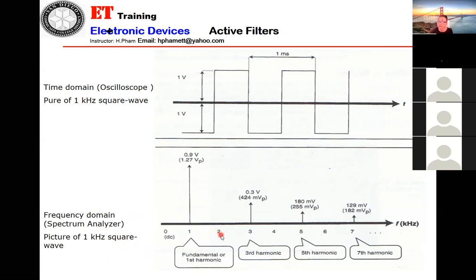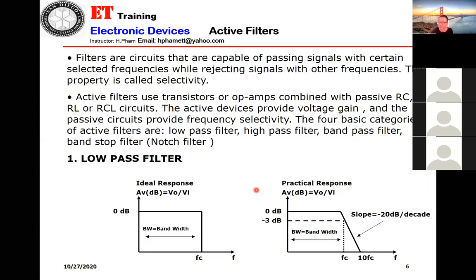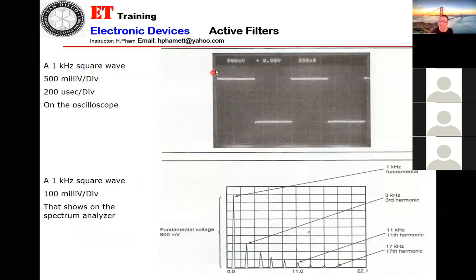They do not display the even harmonics, they display the odd harmonics. Basically, they are telling you at this frequency, 3K, what the value of the signal is. Then 5K, and 7K, the 7th harmonic. That only goes into detail when you learn RF, radio frequency. Same thing here, they just copy it to display on the scope and on the spectrum analyzer.